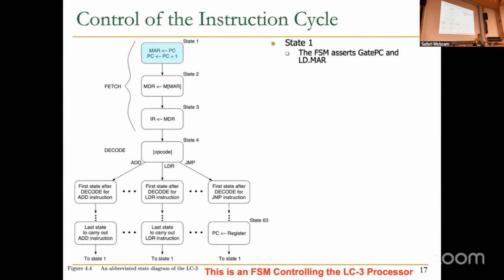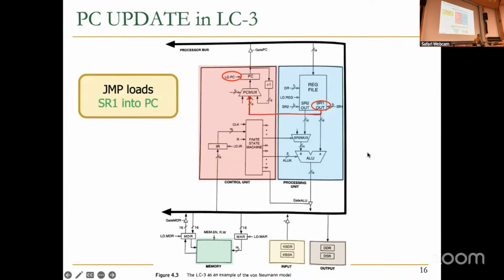So there's something else that's asserted. If we go back to that over here, switching between these two is too much overhead. But essentially what we do here is in the fetch state, you take the program counter, increment it by 1, and you need to have data path elements to enable that. The PC mux, this multiplexer, should select this input, and load PC should be asserted so that you actually increment the program counter by 1.